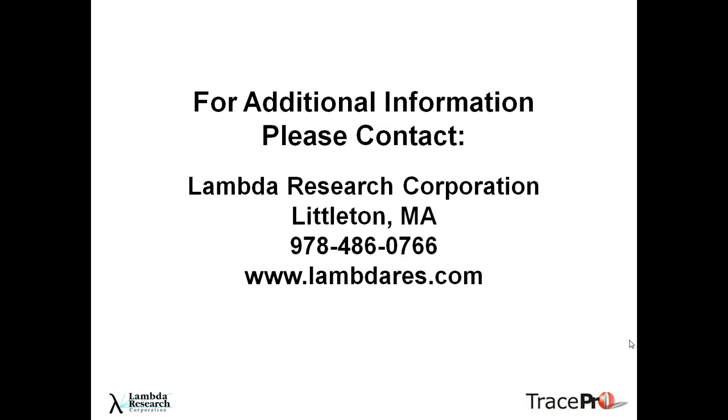We also have a webinar on the website that you can go through, and it talks completely about the ray files that we use and what the formats are. Our ray file data has 2 formats: an ASCII format and a binary format. The ASCII format has a 7-row header that specifies that it's a ray file, and after the first 7 rows, it has row after row of ray data, which is only 7 pieces of information. That's your XYZ position, your XYZ direction vector, and the flux associated with that ray.